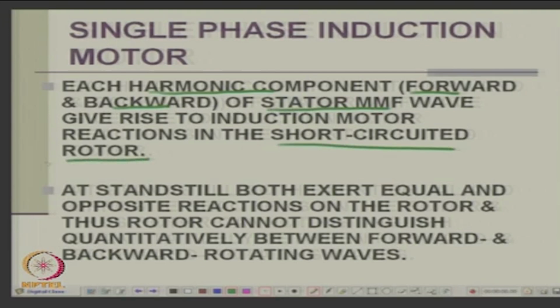We have also said the rotor is symmetrical and polyphase, squirrel cage or wound rotor; the reaction may be slightly different. So, each stator MMF will cause a rotor current, and that will produce a rotor MMF, and this resultant will give you the flux.